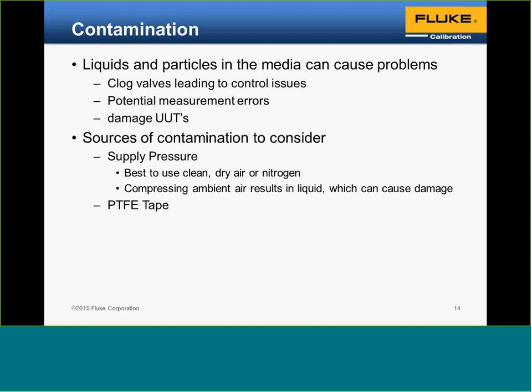Directions. The amount of PTFE tape that you use matters. If you wrap it multiple times, that's not going to help any. That just increases the chance that it'll get in the system.